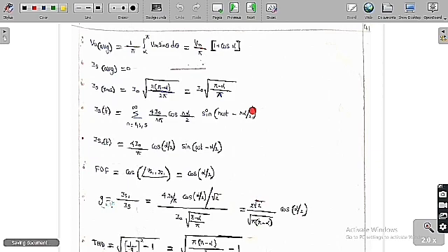So here, in the previous one, the source current expression for the full wave bridge rectifier is sigma n = 1, 3, 5 up to infinity of 4 I naught by n pi into sine of (n omega t minus n alpha). Whereas here there is an extra factor: keep a division by 2, and cos of n alpha by 2. Everything else is the same. So n alpha by 2, take the same term, keep a cos here, so cos of n alpha by 2, and remaining everything is the same.